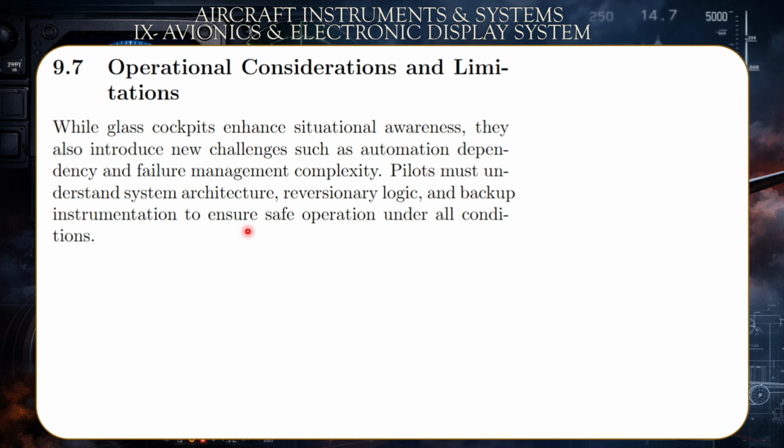So if the PFD and MFD fail, pilots should be able to rely on and understand and read the other instruments that are backing up the PFD and MFD, which is the primary flight display and the multifunction display. PFD is part of the MFD actually. So in case of a failure, and more than that, when you have an emergency that requires a manual operation, the pilot should be aware to disconnect the autopilot.